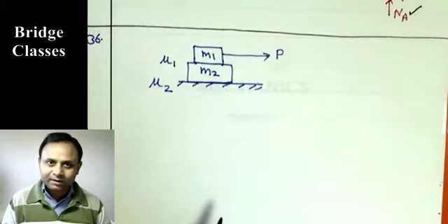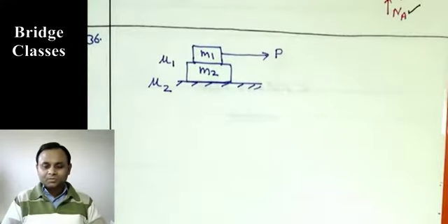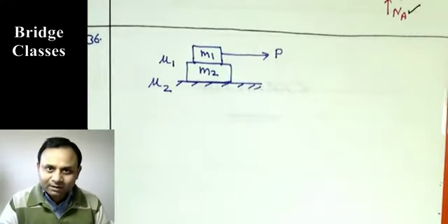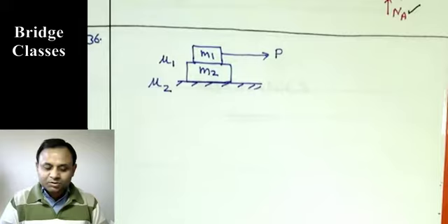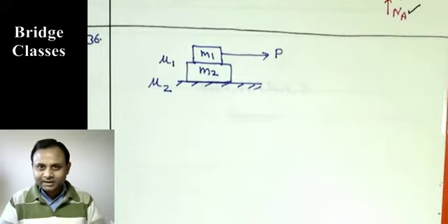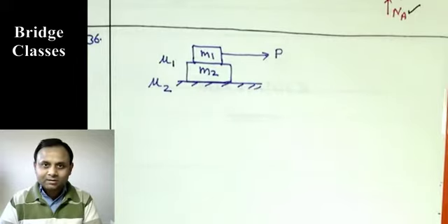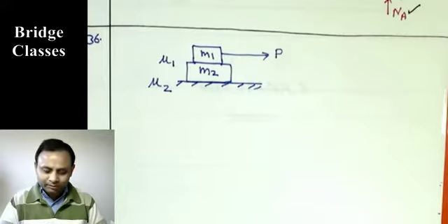So we don't have to test whether tipping occurs, because in a previous problem, I hope you understood when I explained that there is a possibility that the body can tip before it begins to slide. That is the situation when the normal reaction reaches the extreme point on the body. It cannot move any further, but slipping has not yet started, so the body is going to tip.